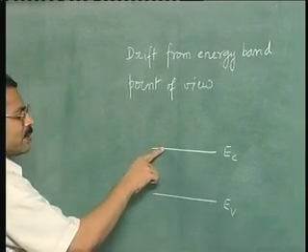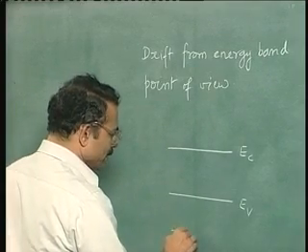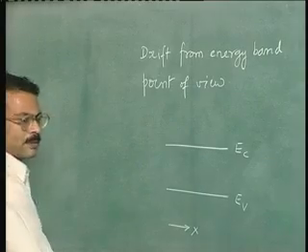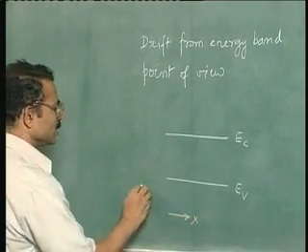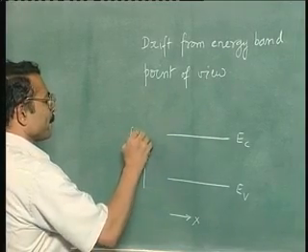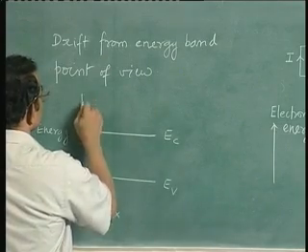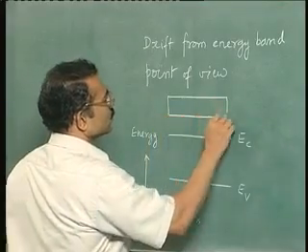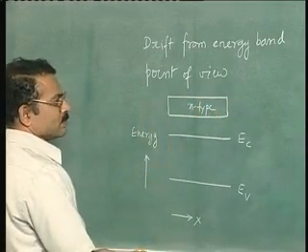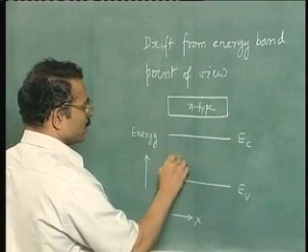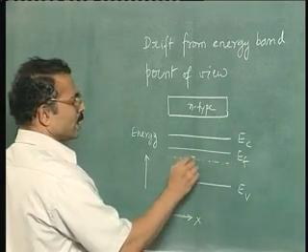This is the potential energy of the free electron, this is the potential energy of the hole, okay, and this is the first time that the diagram is drawn with distance as the x-axis, okay. So this is energy and this is distance along the sample. So this is a sample. No electric field is applied. So these are under equilibrium conditions. So your Fermi level here would be somewhere here, this is Fermi level. This dotted line shows the intrinsic level.